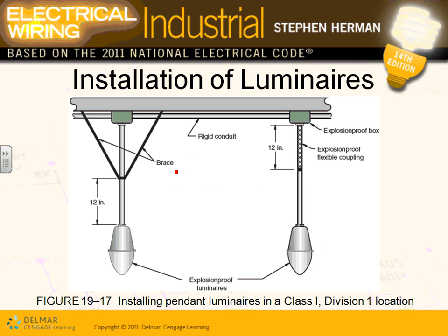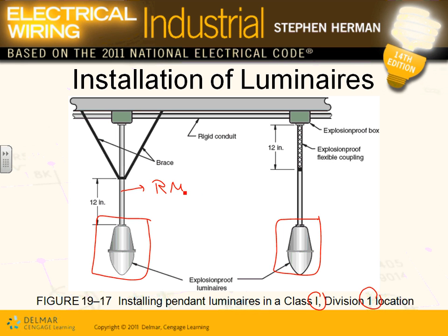Luminaires, guys, there are two ways. Luminaires in a Class 1 Div 1 location, you can do them in two ways. Here's my explosion proof luminaire, right? You try to avoid it, but because of Class 1 Div 1, I have to have explosion proof. I have two options. Option number one, guys, is to use rigid metal conduit. Then you have to support it within 12 inches. These are all code, so it doesn't swing. So you have to support it with the brackets.